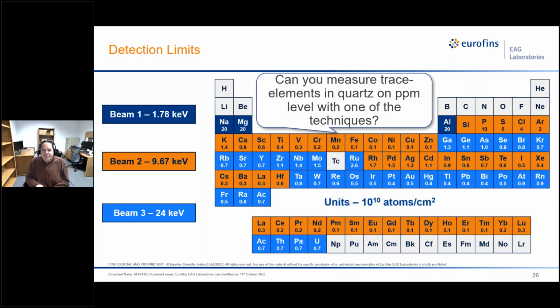There was a question asking why it was difficult to detect lighter weight elements with TXRF, and the answer to that question is kind of a mixture of a limitation of the technique and current tools. It's hard to get a strong low energy peak as an incident beam on the sample to excite lighter elements. And with the lower energy fluorescent X-rays, it's harder for detectors to pick them up as well.